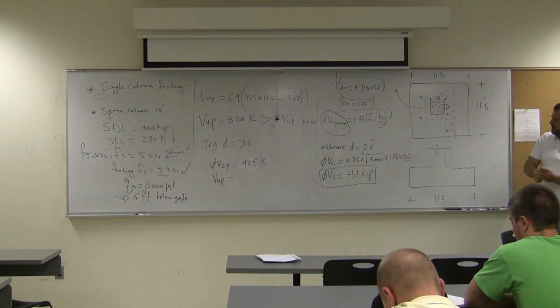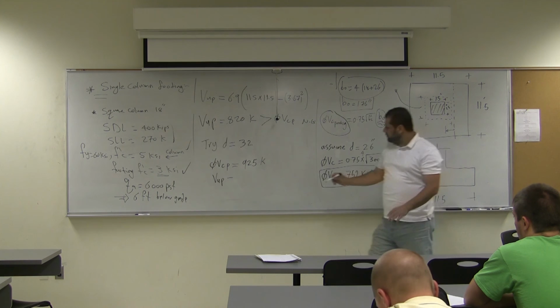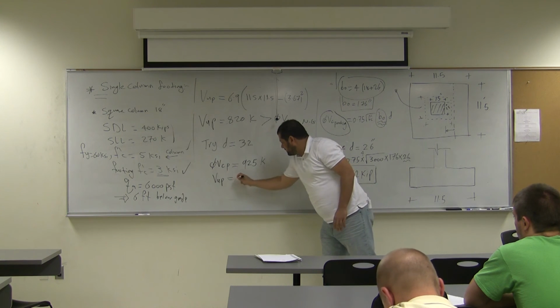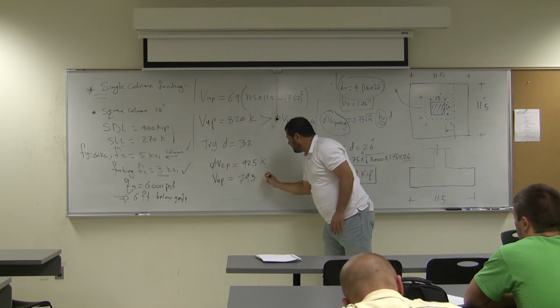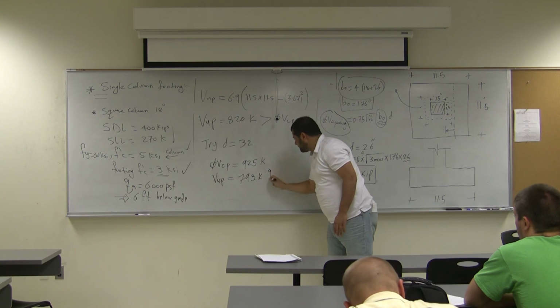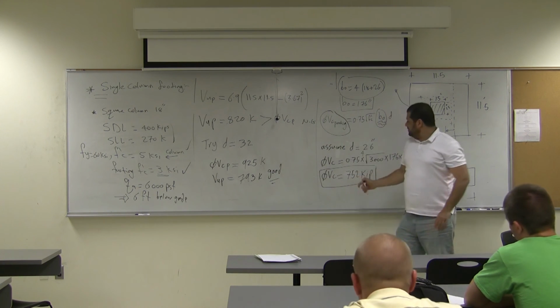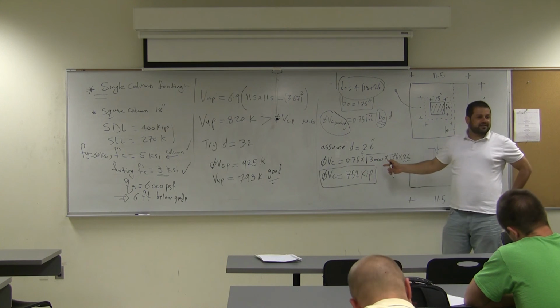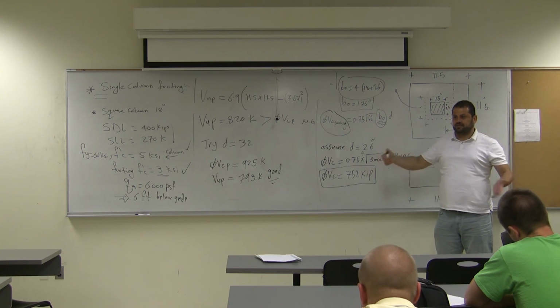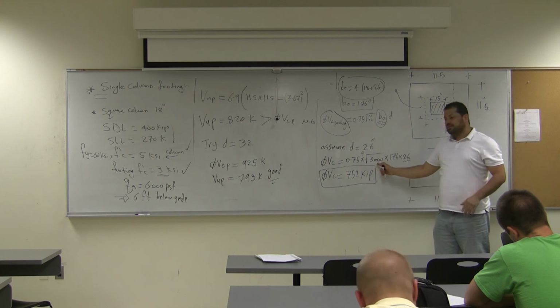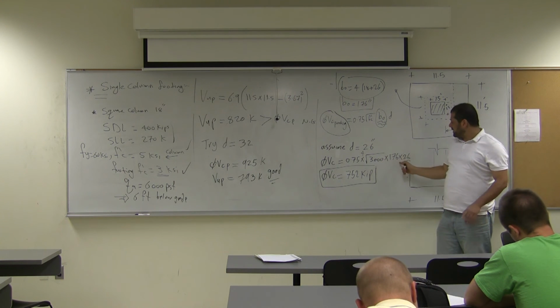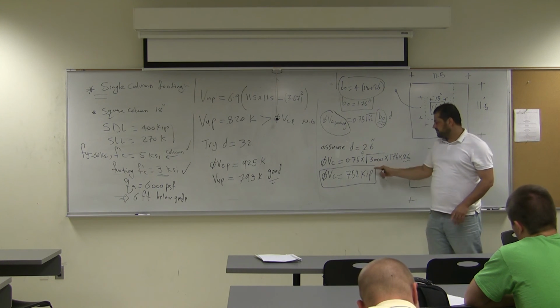So you get 793, we are good, right? Wait, before we go, by the way. 793, good. So this thing is good. By the way, before we go, look, if this one was 4,000 psi concrete, if you are a designer starting things from scratch, you put the specification for that. If this one was 4,000, with the 26 as is, how much do you get, by the way?